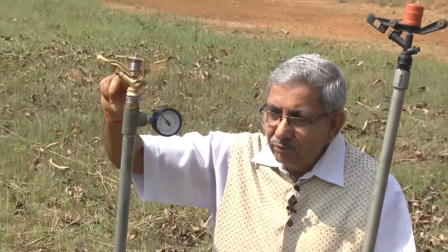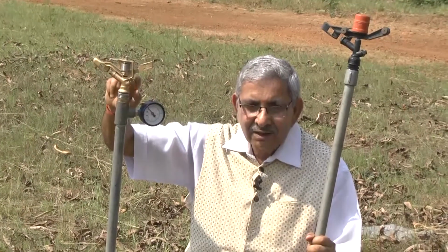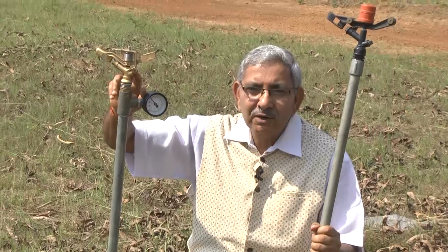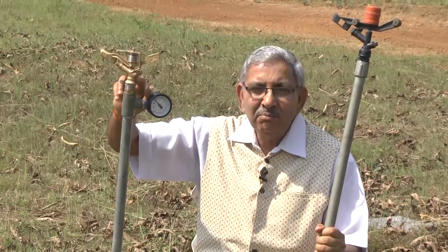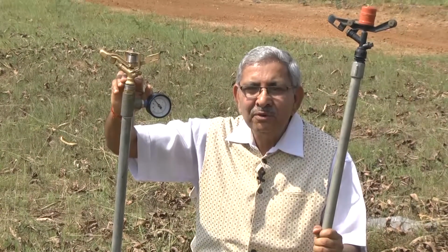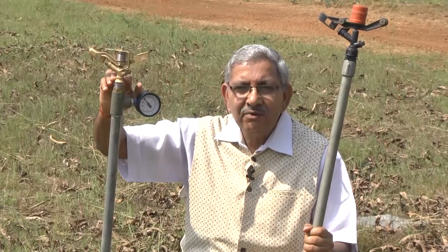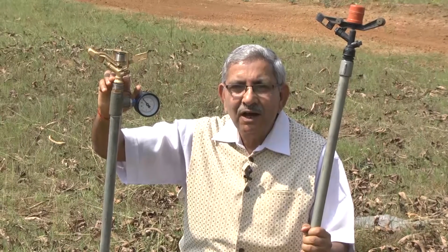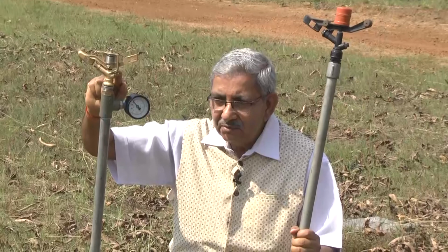Now, we will be monitoring the pressure, and at a given pressure, how much discharge is coming out of the sprinkler. So, there is a relationship which I have already explained to you, that discharge from a sprinkler nozzle is directly related to the square root of the operating pressure. So, we will find out the total discharge, the discharge from this nozzle plus the discharge from this nozzle.